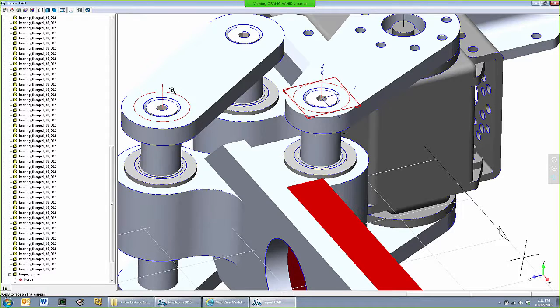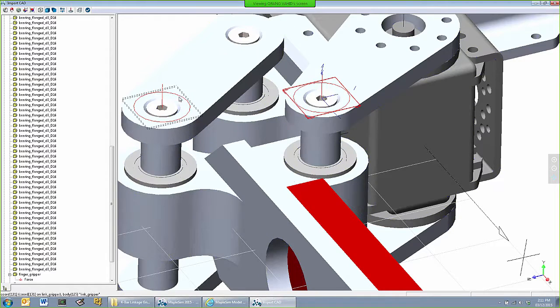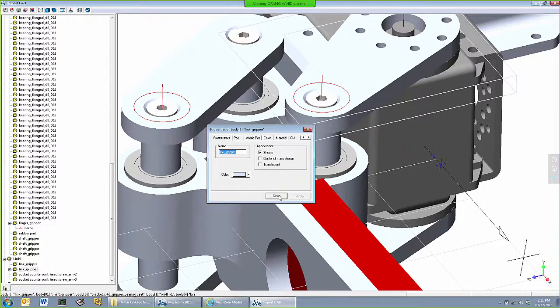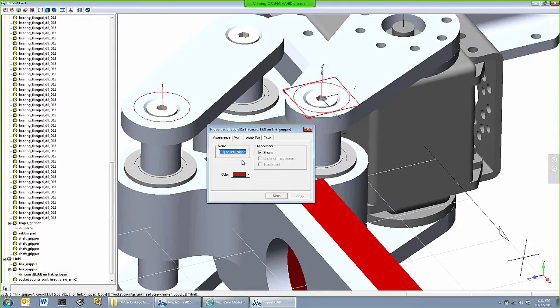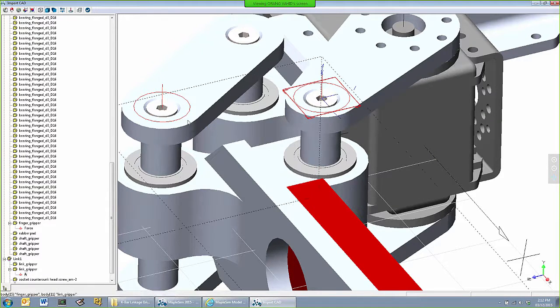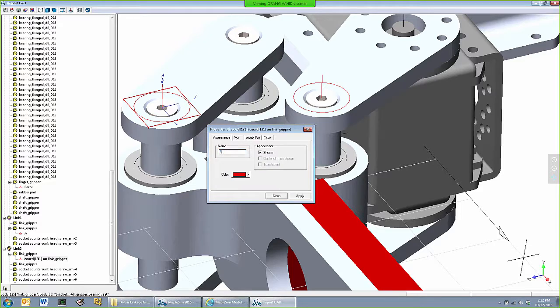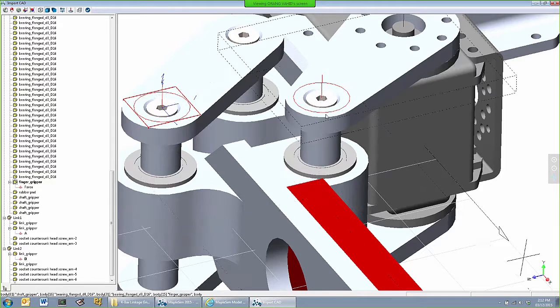So these two coordinates currently belong to the link 1 and link 2 objects. Let's give them a name that we can find easier. I'll call this simply A, and I'll call this B. You can see them on the tree as I make changes. For creating a joint in MapleSim, especially if you have had interactions with the software, there are two multibody frames and a component that sits in between. In this case, we will use a revolute joint. So I need another coordinate.